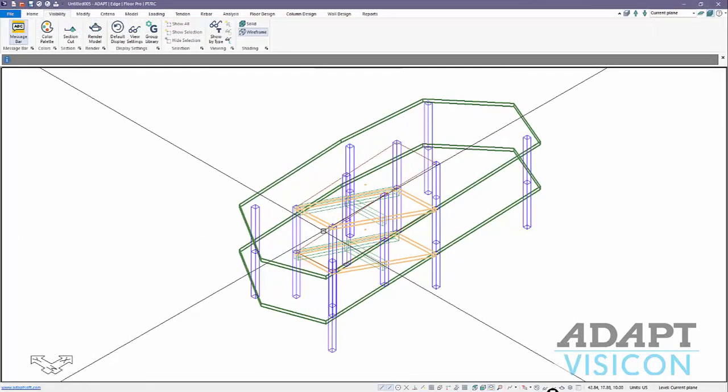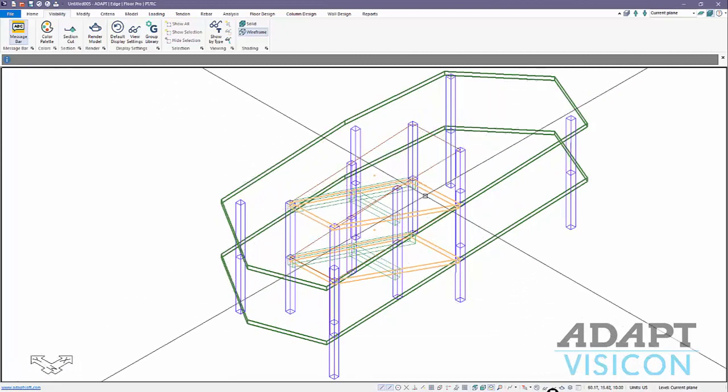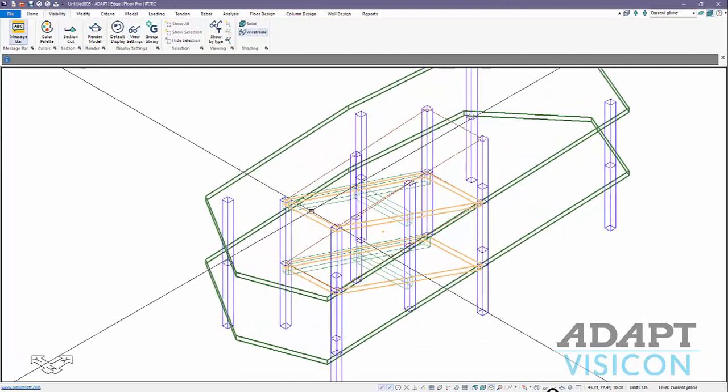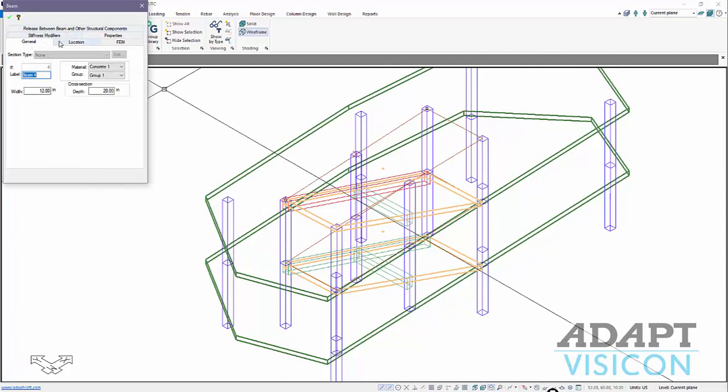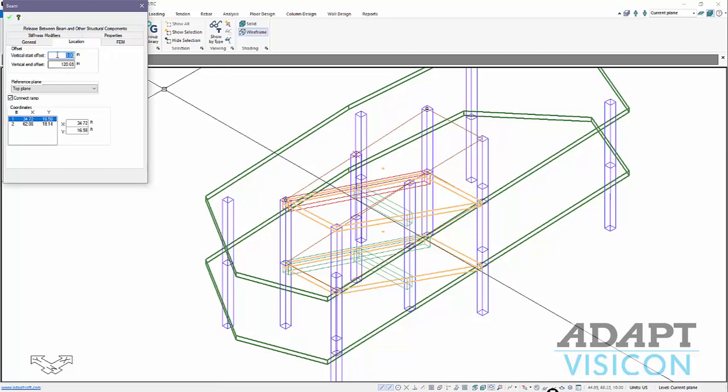The ability to slope columns or beams rather, in this case, requires the ability to support offsets at both start and end point of the beam. So for location, you now have the ability to model beams really as braces. You could apply this to something other than just ramps. You could have a sloped beam member in a model using these offsets.